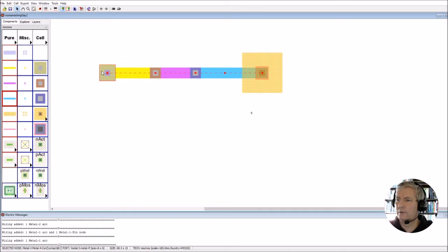In order to get this one, sometimes you have to actually click on this here. So the actual layer. So this is the metal 4. So if I left click and right click, left click, right click. So we're actually on metal 4. So we've gone from metal 4 down through the via to metal 3 to metal 2 to metal 1. And then eventually this will come all the way down to the actual polysilicon.